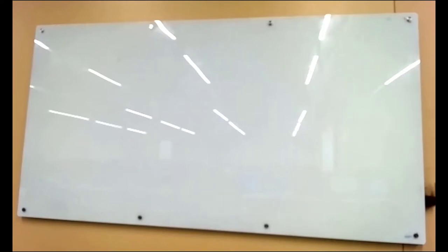All right, so we're going to look at the change in the drag and the pitching moment and the lift due to that pitch rate. And we'll draw exactly that picture, and it's going to depend upon how far the tail is behind the CG, because that's going to determine how fast that's moving through. The further it is out on the radius of the circular motion, the faster it goes down and the bigger the change in angle of attack.